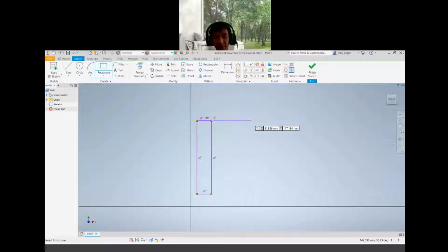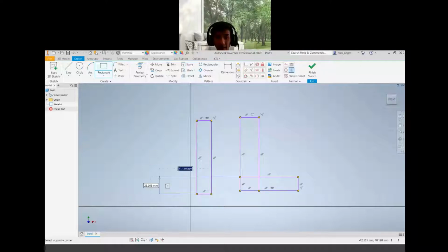If you don't want to utilize this one, you can create one like this also, no problem. But the next one, the most important one, is to create another rectangle to snap towards this endpoint here. Another one here, another one over here also, and last of all, another one over here. Please create these 5 rectangles. Then we are going to apply the geometrical constraints to stabilize the shape before we apply the dimensional constraints, as we did yesterday.